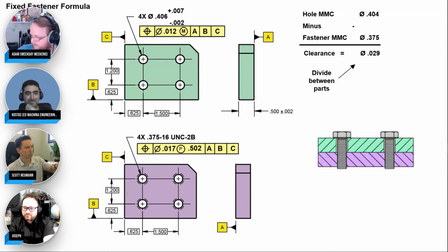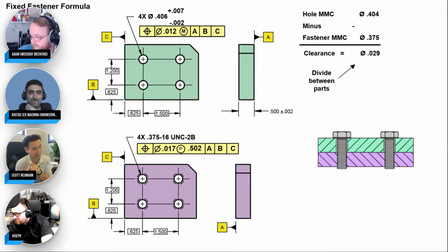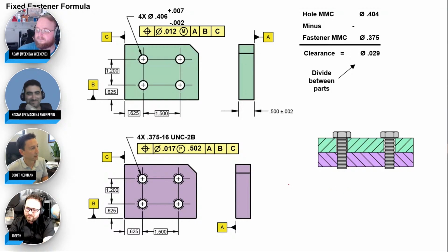Now, if somebody said, well, you need to make it easy to inspect so I go off the minor diameter. Oh, but I don't care about the minor diameter. All right, fine, I'll do that. But I can't give you 17 anymore, because the minor and the pitch might have a coaxiality problem. They might be off 2 thou. So if you force me to do a minor diameter check, then I'm going to reduce the tolerance down to 15. And no, don't reduce the tolerance if that's not functional. So what I'm going to do is put 17 on there.